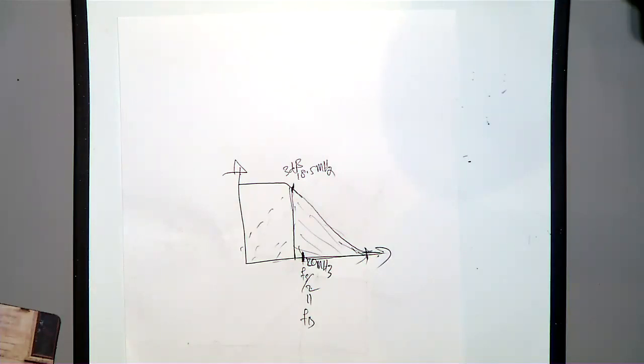So your DSO design is a bit tight. Why we made it a bit tight is because of this reason. For each specification we thought a lot. So now you know that you will be better off with a high frequency ADC, so that you can design a better filter. You know what I meant? Now it is clear. If you increase the sampling rate of your ADC, then you can design a much better filter, because then your stop band is pushed away.